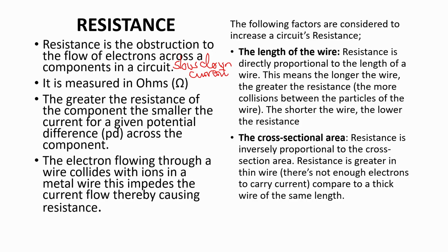And again, I think you've got here lots of good stuff. Just watch your capitalization there. You're right, resistance is directly proportional to the length of the wire. That's nice. In fact, that's a nice link to the fact that when we're putting resistors in series, it's a bit like making a longer and longer wire, because each individual bit of the wire is like a little resistor. So therefore, the more resistors in series is like having a longer and longer wire.